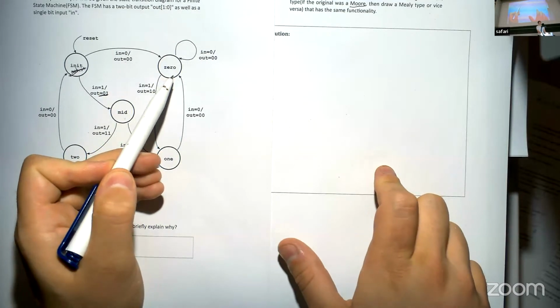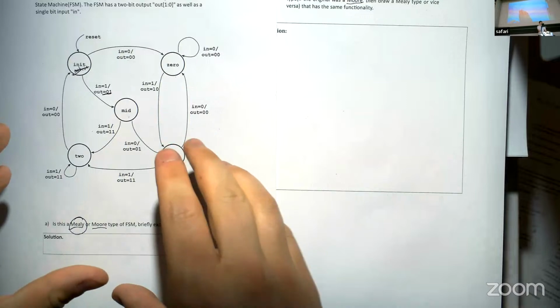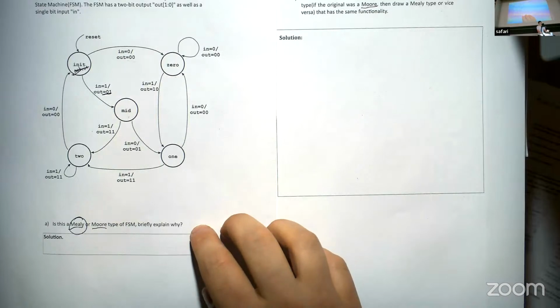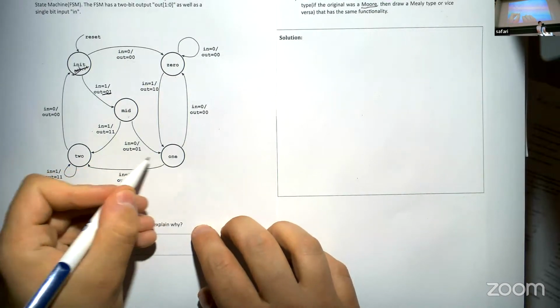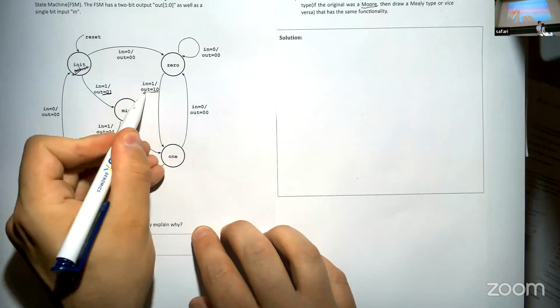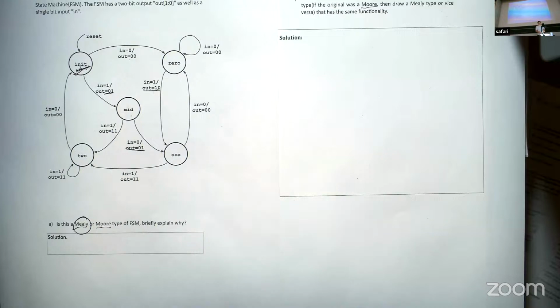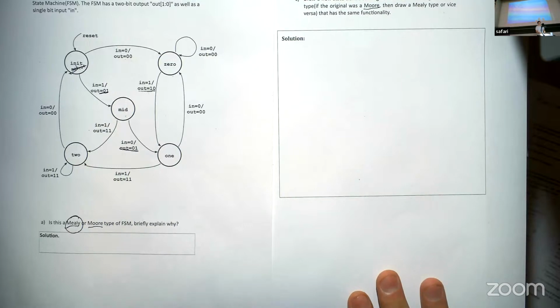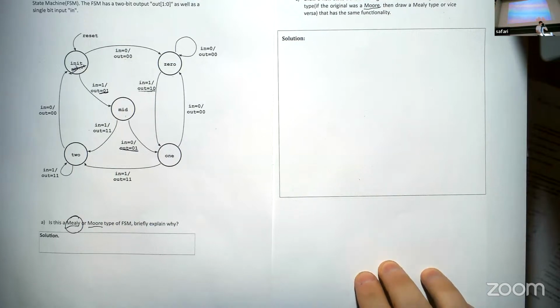some of these edges, if we were to take this exact FSM and just write the outputs into the states, we might have some states, for example like this one, that has 2 ingoing edges that are supposed to result in different outputs. But in a Moore type FSM, the same state can only produce 1 output. So we need to come up with a solution there. The solution is quite simple. You introduce multiple states if you have multiple ingoing edges with different outputs. Let me show what I mean here.